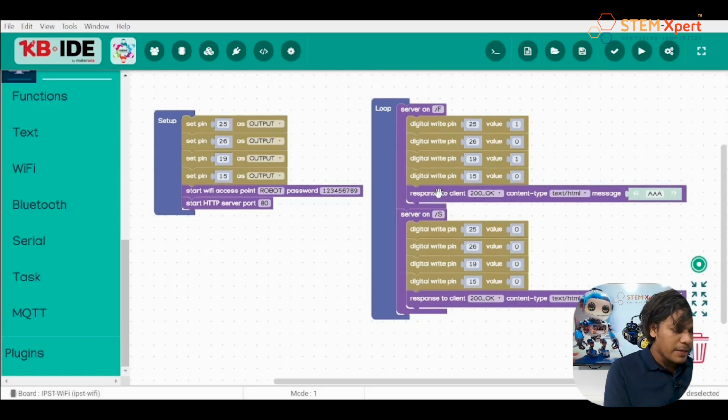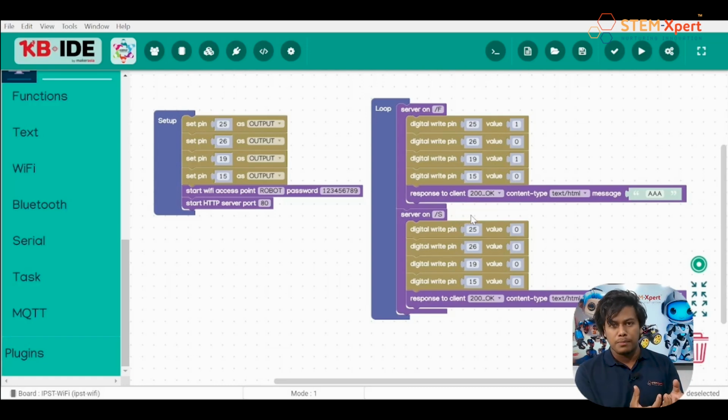And just below you can see something like server on S comes, which means if a command called S comes, the robot has to stop. That's why here we set all ports as 0, which means negative. Then it won't move actually. That we learned, right? Just keep in mind, if you set 0, 0 for a motor, the robot won't rotate, which means it's like a stop stage.